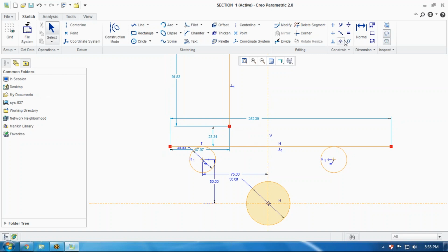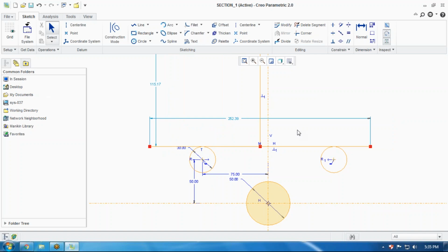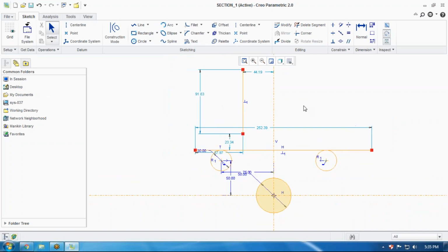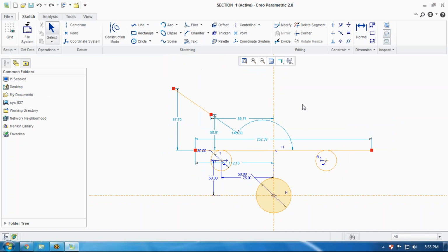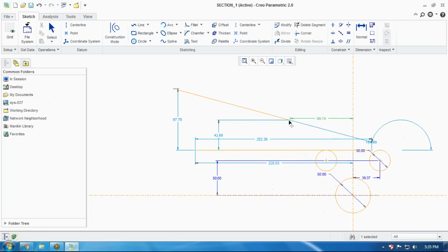If you want to make it join also, go for midpoint or some coincident command, that's all. They will be in the perfect relationship. Now the next command here will be parallelism. I'm just dragging the position of this line anywhere on the screen.